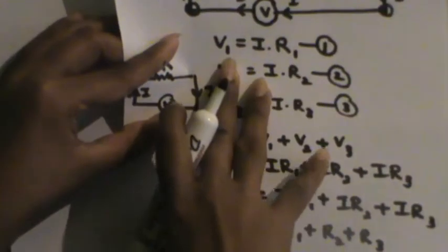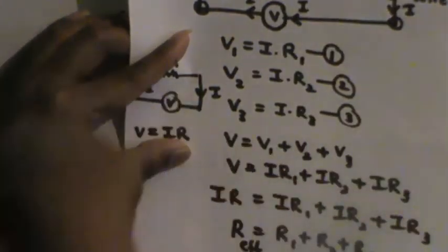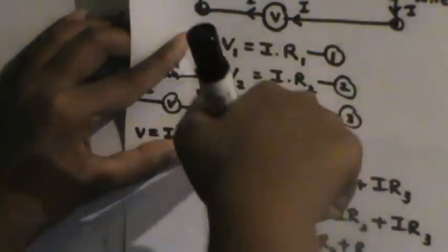So these resistors are actually in series, because the same current is flowing through this circuit. So I'll take the value to be I, and in that direction. There are two ways to find this. Either find the voltages from the equation that we got, right? So from the way we got V1 equals IR1, find V1, and then find V2 and V3, and then equate the sum to 8 volts and find the value of I, because R1, R2 and R3 are given.